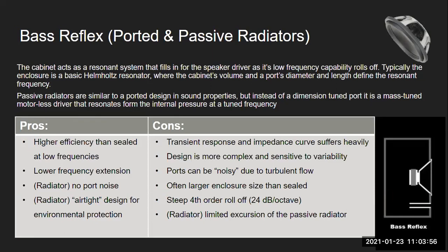What's cool about this is it really does allow you to extend the low frequency abilities of the speaker pretty far beyond what it would do on its own in a sealed configuration. I have a comparison on the next slide, which I can show in a second. However, the roll-off is much steeper. It's a fourth order roll-off, 24 dB per octave. So you play down to a frequency, and then after that, there's not much. It tends to have higher efficiency because you're not trying to overexert the driver, so you get some benefits there.